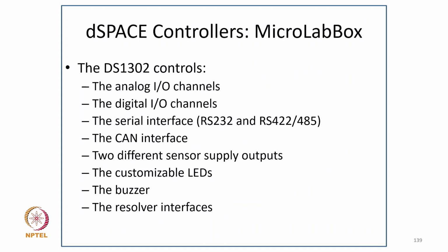So the DS1302 controls the analog input-output channels, the digital input-output channels, the serial interface RS232 and RS422/485, the CAN interface, two different sensor supply outputs, the customizable LEDs, the buzzer, and the resolver interface.